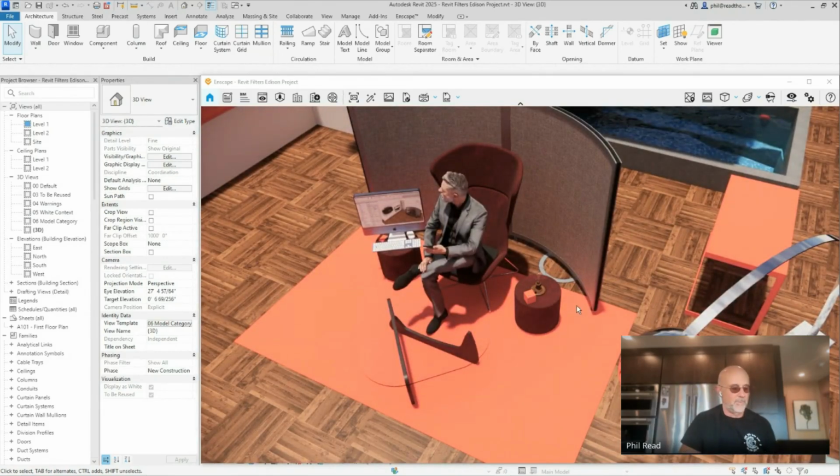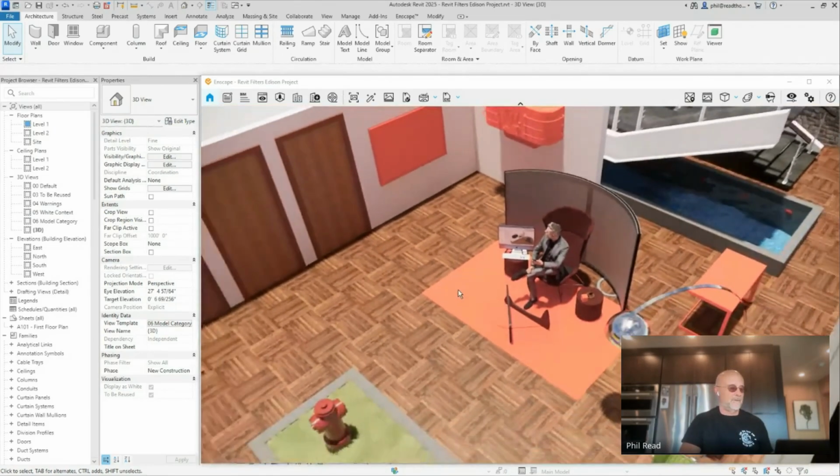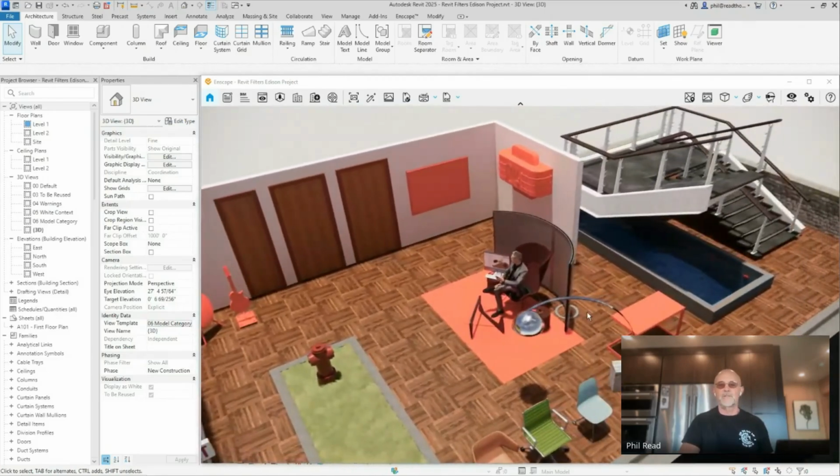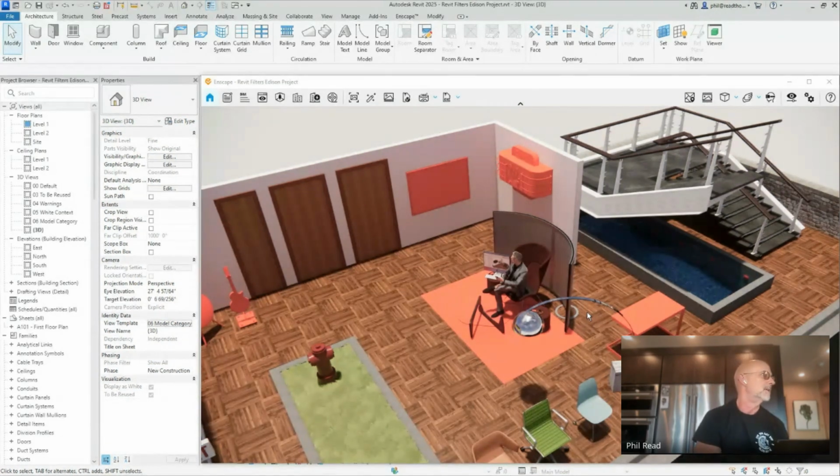That's okay. But I don't know how many times I've looked at schedules and went, yep, it's scheduled, it's automatic. And then you realize someone built something on the wrong category. So you could use this to check that things that are furniture are actually on the furniture category, or what's the other furniture? There's two furniture categories. You want systems furniture. So you want to light all that stuff up and then walk around. And if you see something that's not highlighted red, you go, whoa, wait a minute. What category is this thing?